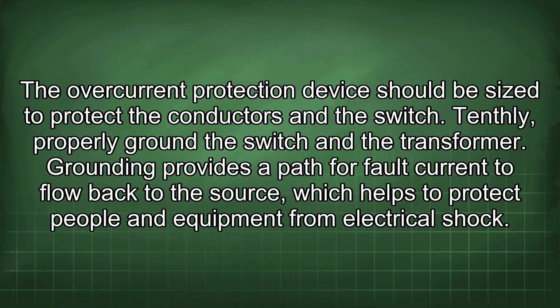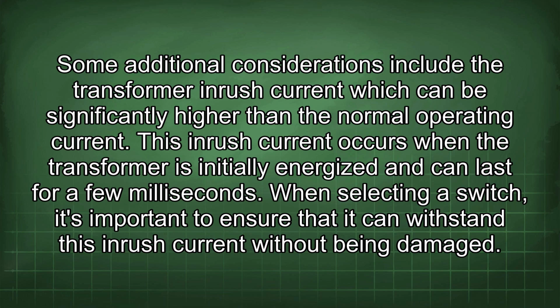Some additional considerations include the transformer inrush current, which can be significantly higher than the normal operating current. This inrush current occurs when the transformer is initially energized and can last for a few milliseconds. When selecting a switch, it's important to ensure that it can withstand this inrush current without being damaged.